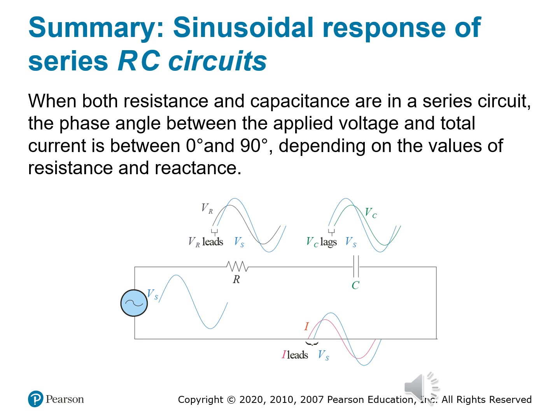When you wire a resistor and a capacitor in series, and apply a sine wave, the circuit responds in a uniquely smooth way. So the current leads the applied voltage, but it doesn't go to the full 90 degrees like a pure capacitor would. Instead, the phase angle lands somewhere between 0 and 90 degrees.